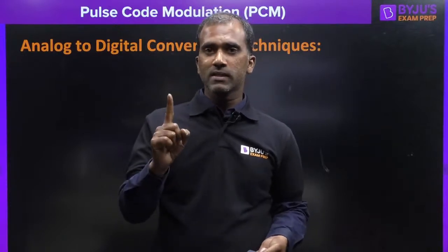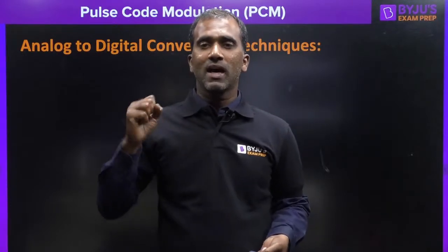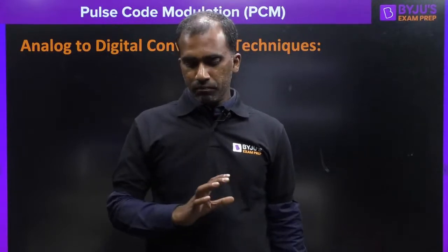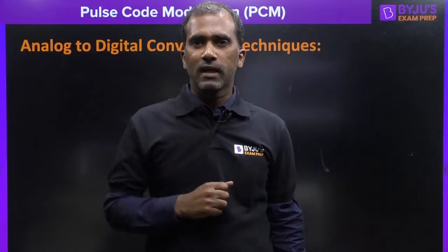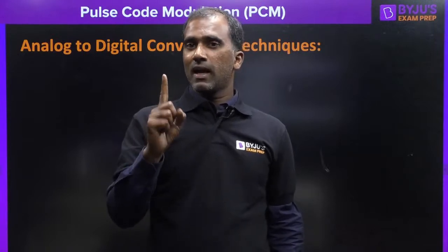One reason is we don't have circuits that can process higher frequencies. We are capable of communicating signals up to 10 gigahertz, 20 gigahertz, or up to 50 gigahertz also, but not more than 100 gigahertz. More than 100 gigahertz wirelessly, we don't have equipment to do that. Right now, we don't have equipment. In future, we might discover it and be able to communicate with higher frequencies, and then we'll get more bandwidth. First reason is the lack of circuits that can process higher frequencies.